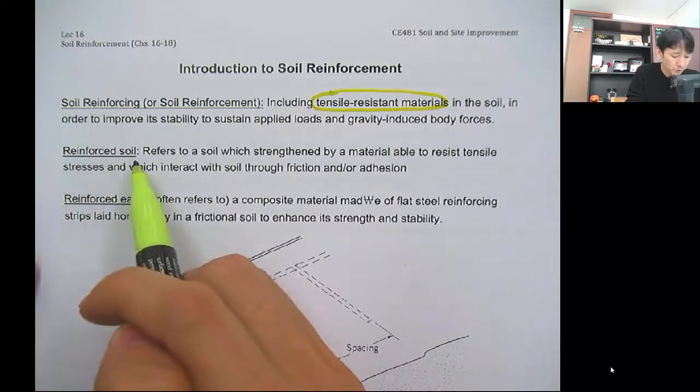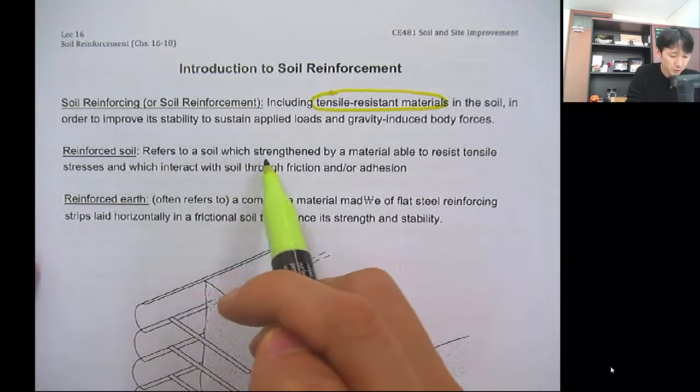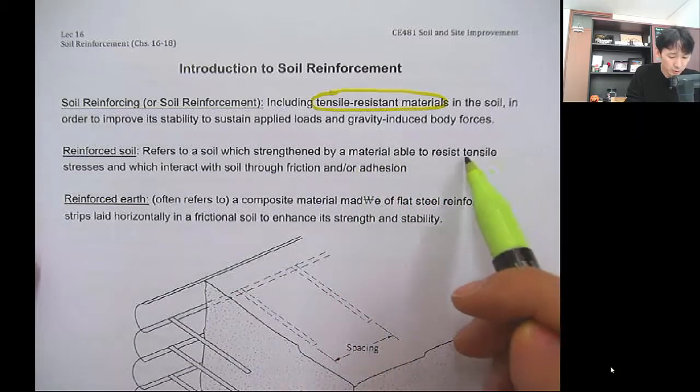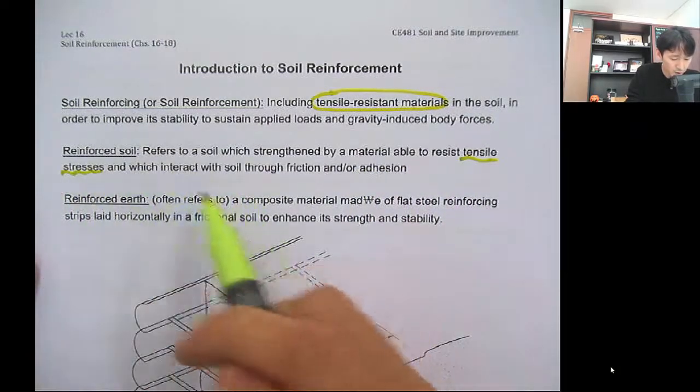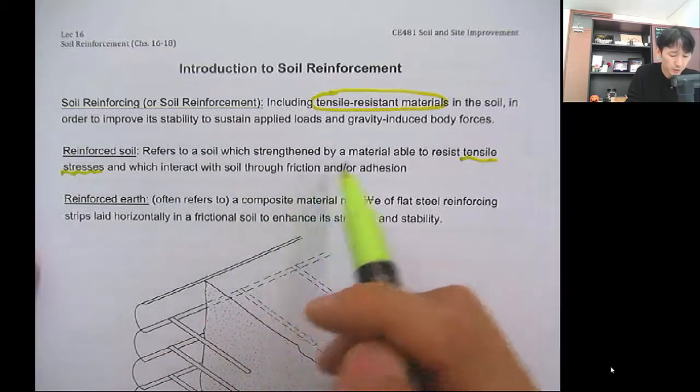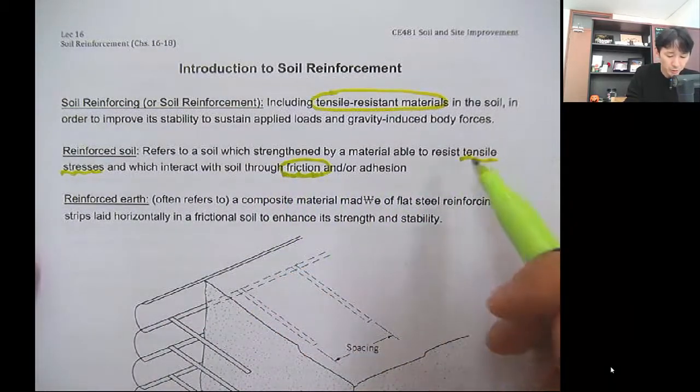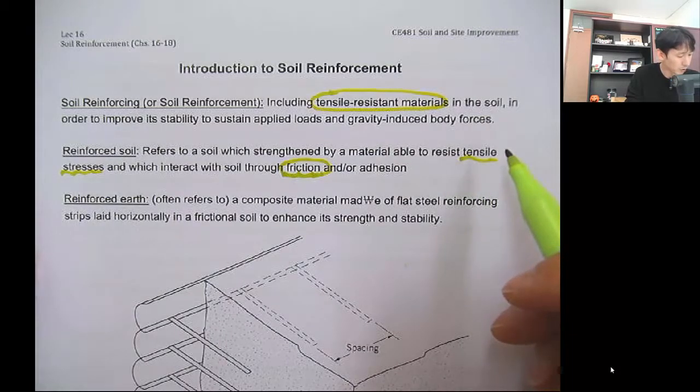Reinforced soil refers to the soil which is strengthened by a material able to resist the tensile stresses and which interacts with the soil through friction and adhesion. So also the keywords are tensile strength or tensile stress, and friction.